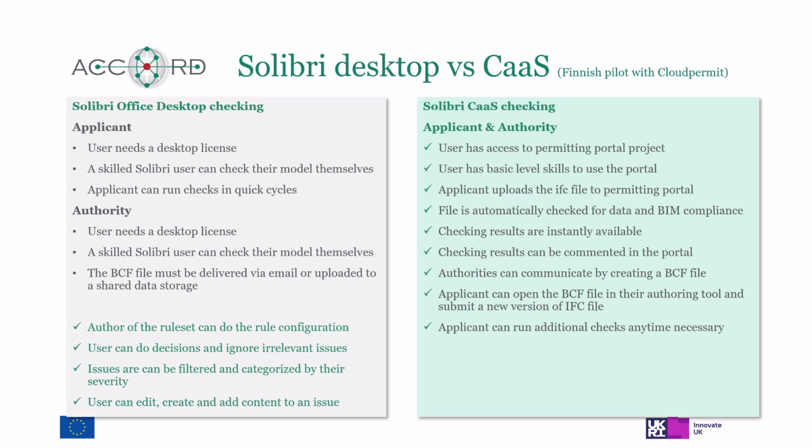Checking results can be commented and communicated by creating the BCF file. The applicant can open the BCF file in the authoring tool and submit a new version to the portal again. The applicant can run additional checks anytime necessary.